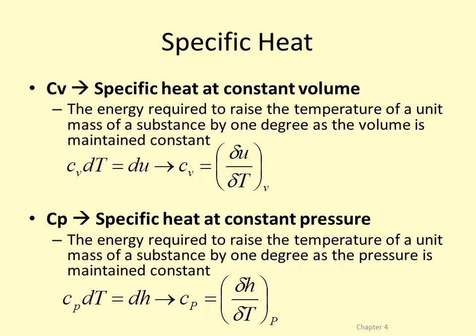So the change in internal energy is going to be the same regardless of whether it's from state 1 to state 2, because internal energy is based on the initial and the final temperature, and the same thing for the enthalpy. But what you're calculating when you calculate the internal energy is just that internal energy change. And when you're calculating with the enthalpy, you're calculating the internal energy plus this flow work and/or expansion term.